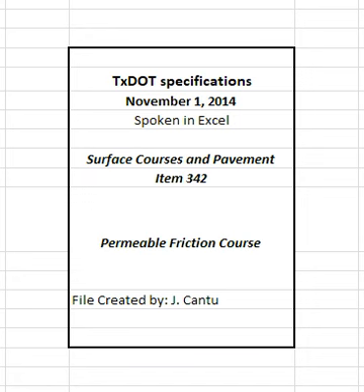4. The contractor may reduce the amount of fibers to no less than 0.1%, provided the mixture meets the drain down requirement, when at least 3% RAS is used in the mixture. 5. Unless otherwise shown on the plans or waived by the engineer based on Hamburg wheel results. 6. Used to establish baseline for comparison to production results. May be waived when approved.